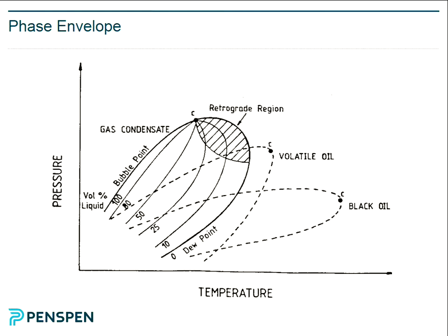So as you go down the well tubing, go down the pipeline, you drop down into here, you get condensate forming. That's where you hit multi-phase flow. That's the significance of multi-phase flow. But it's quite possible you can pop out the bottom. So it's quite feasible that you can have single phase in, multi-phase flow in the pipeline, and single phase out. I've actually come across that before. It's very inefficient, but quite perfectly feasible for that to happen.